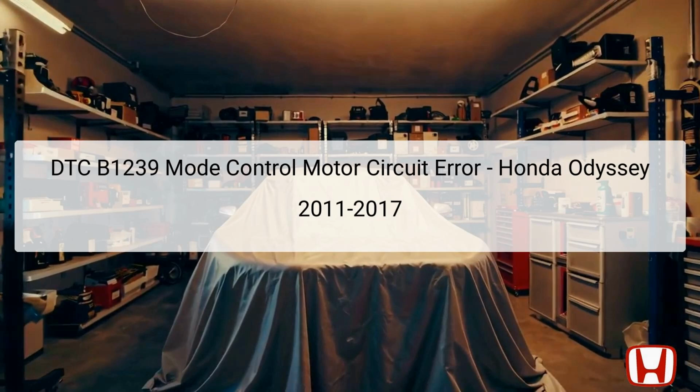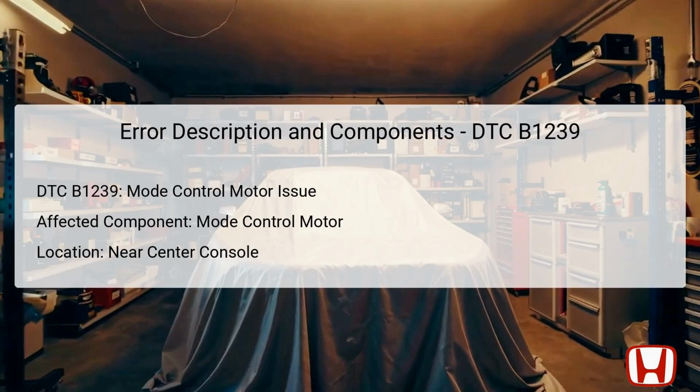Its location is typically near the center console, and it operates based on commands received from the climate control unit. Proper functionality ensures that the climate control system responds adequately to the driver's settings. DTC B1239 indicates a malfunction associated with the front mode control motor in the Honda Odyssey.